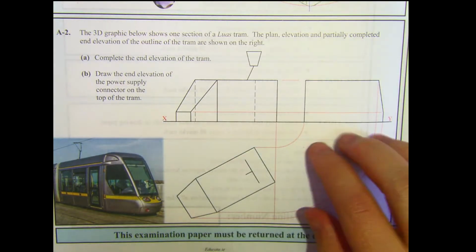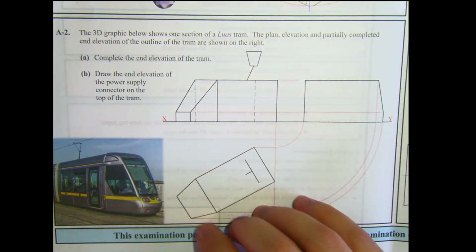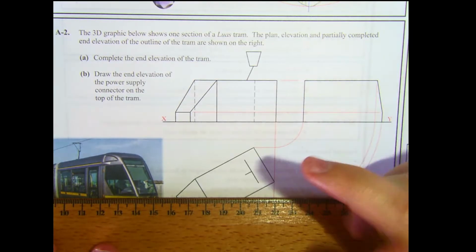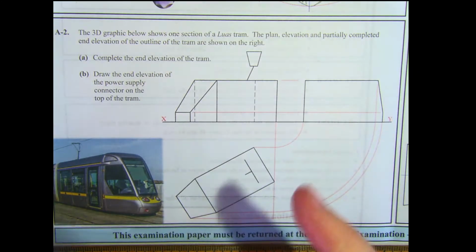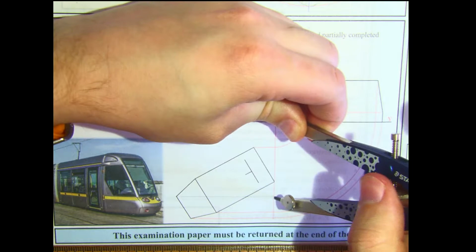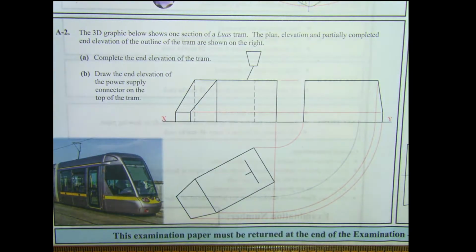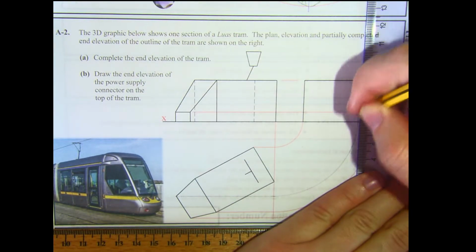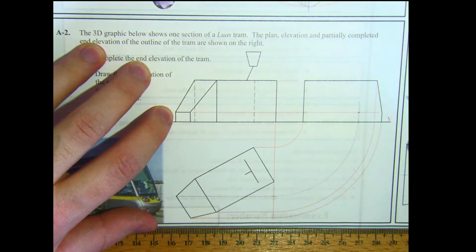So what we need to do is change or draw the front part of this here. Taking each piece, this one across, rotate it around just like all the other points have been. This point here rotates and then can be projected up at the correct distance. So this point here is at the front, so this is going to be this point on the front of the tram.